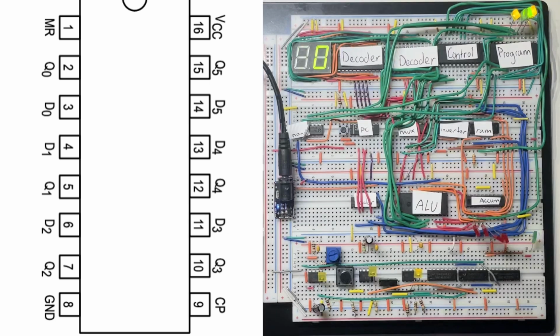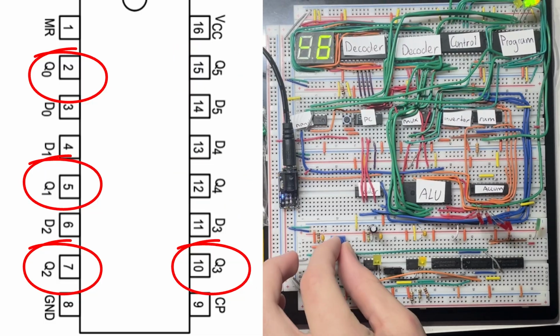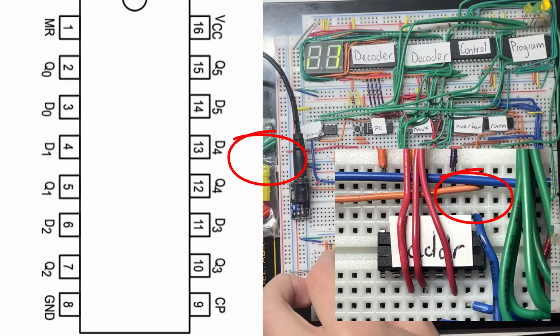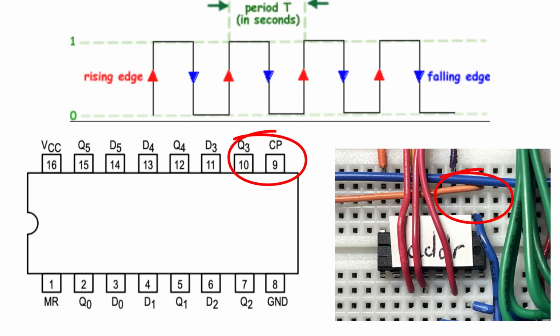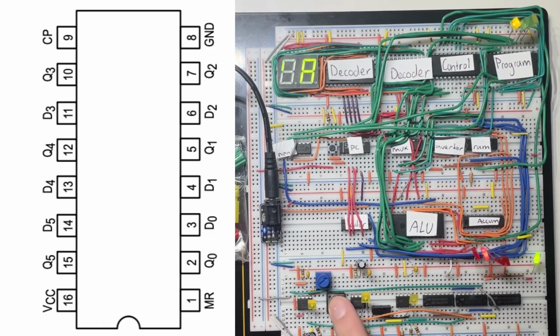Memory addressing is handled by the 74LS174 address register. This hex D-type latch captures the value on the data bus and holds it steady across 6 outputs. 4 of those outputs are the address lines for the RAM. The register updates only on the rising clock edges when enabled by the control word, ensuring the addresses remain stable throughout each load or store instruction.